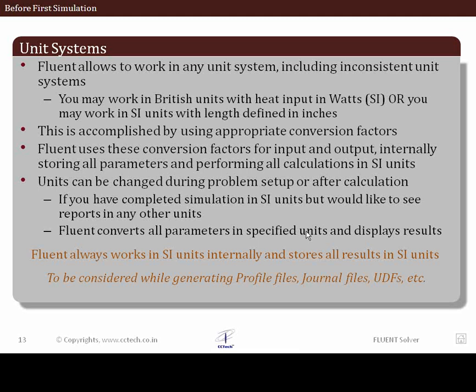When it comes to unit systems in Fluent, it's very helpful to know what kind of units Fluent can accept. Fluent can work with inconsistent unit systems. So you can have, let's say, length defined in meters, and power defined in another unit like watts, which is also SI, or you can have pressure in bars or in PSI, and you can mix the British and SI unit systems or many other unit systems.